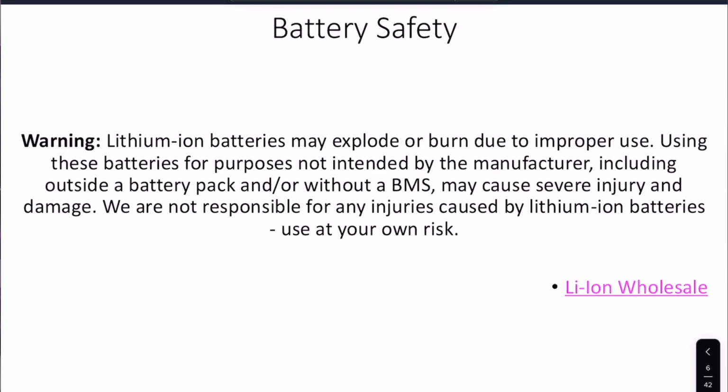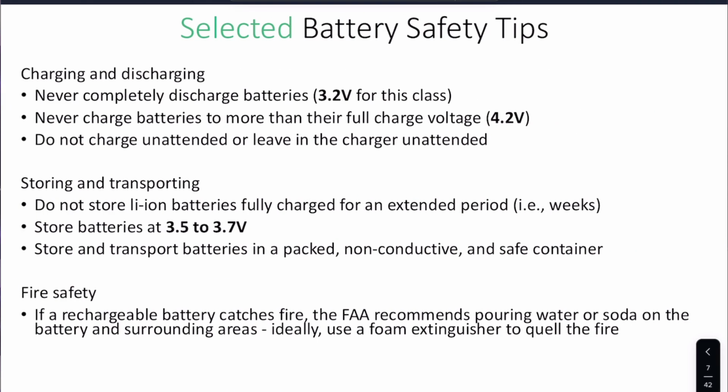Lithium-ion batteries are fairly safe, and I bought extra safe batteries, something with a protection circuit built in. But it's very worth knowing that you should treat them with some respect. There's a lot more information listed on the course website, which is why I just have this called the Selected Battery Safety Tips. You should definitely read what's on the course website. But I don't ever want you to discharge the batteries below 3.2 volts, and I will only ever charge them to about 4.2 volts.